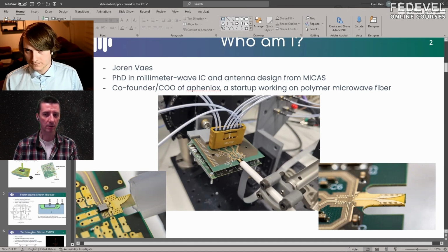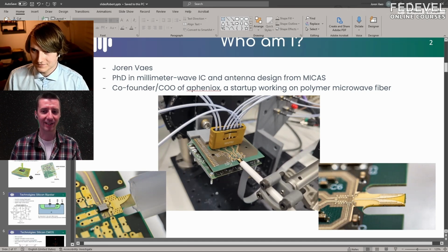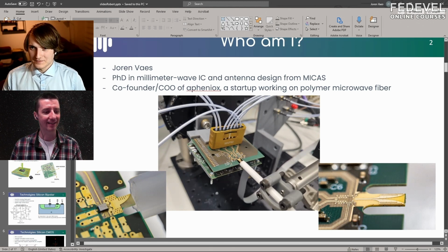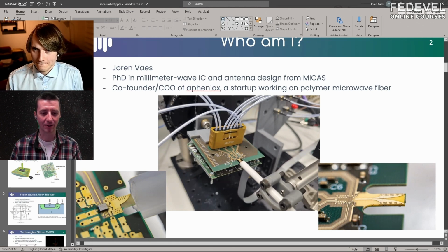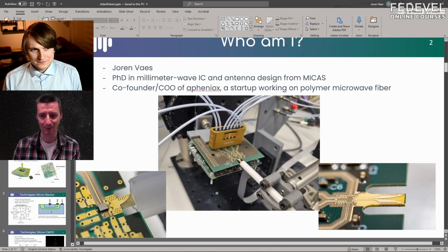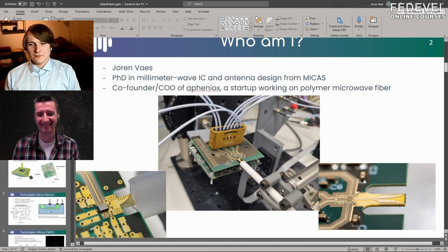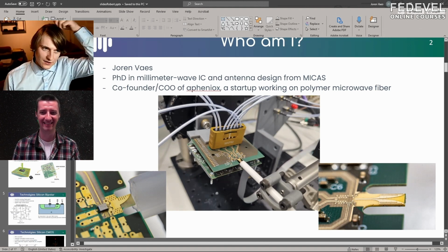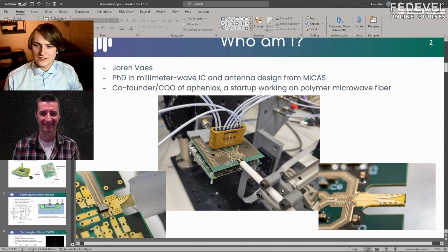But that's good because I don't use chips very often. I try to handle the boards the way customers may do it, so no ESD protection or anything. I really would like to find out as soon as possible if there is a sensitive chip, and then I never use it. The problem with ESD is that a lot of people think it's a binary condition, right? So either a transistor has or hasn't failed.